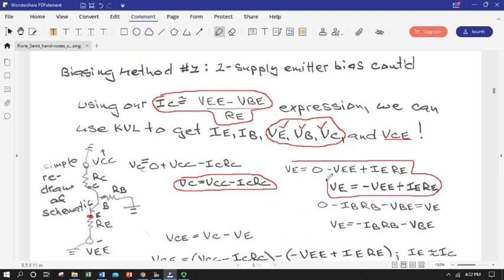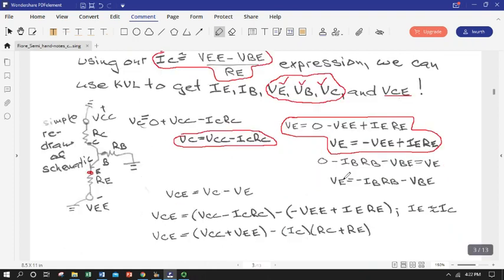So we're just applying Ohm's law to the circuit, and we can have an analogous expression for V sub B, going from the base, because we know what the voltage drop base emitter is. So it can go from ground at 0. We can drop our base current times our base resistor. We can drop the base emitter voltage and arrive at point E by a different route.